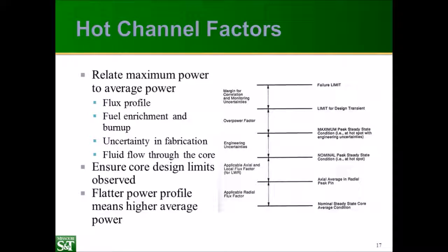We also have to look at the core flow behaviors. You can have coolant mixing between assemblies in a PWR, and in a boiling water reactor, in between the fuel cans, there's some small gap between the fuel bundles. You can also have mixing, especially in PWRs. Flows from the hot channel may be redistributed to cooler channels. Typically, these two factors are evaluated through testing or CFD rather than theory.